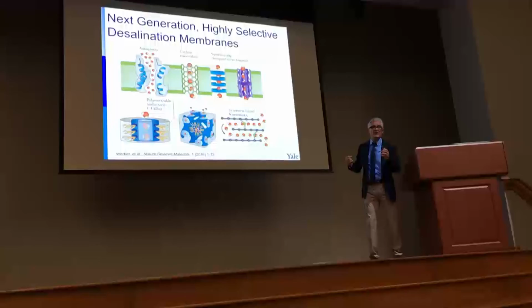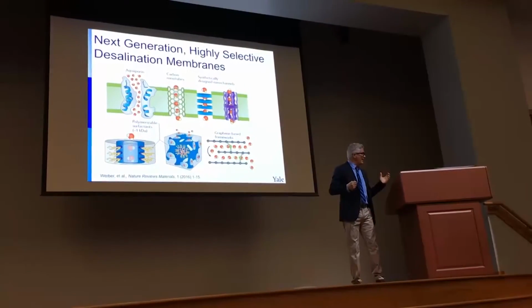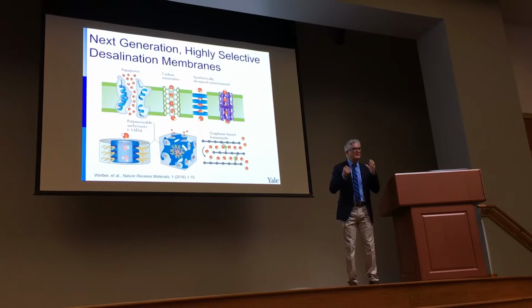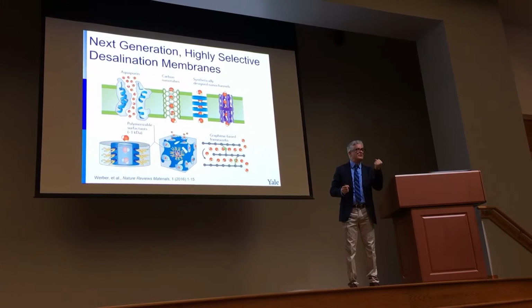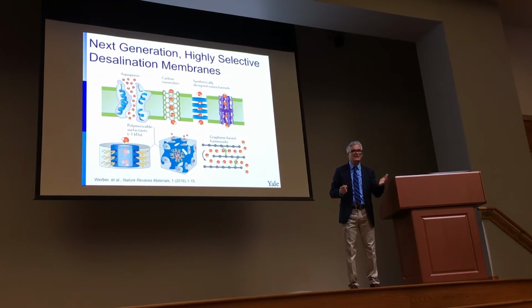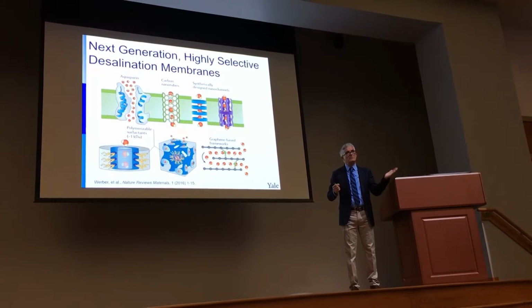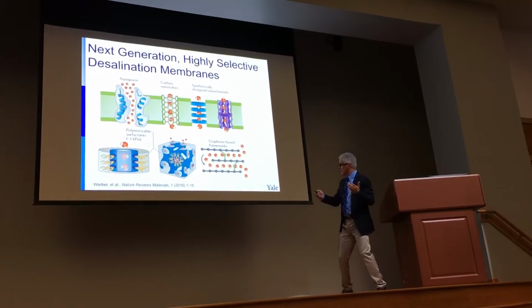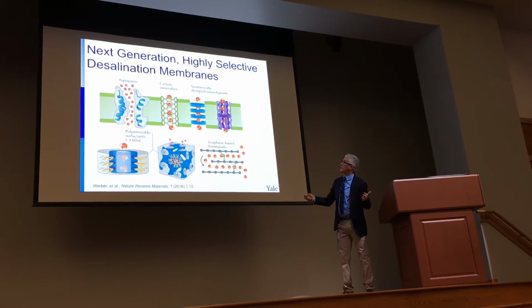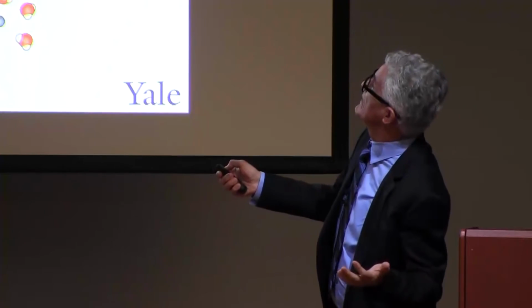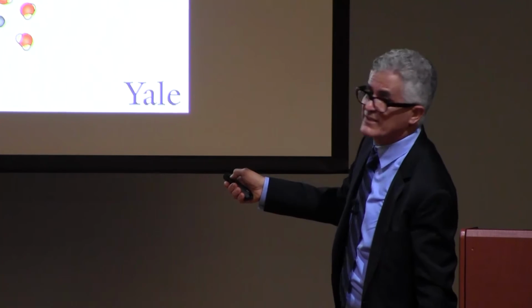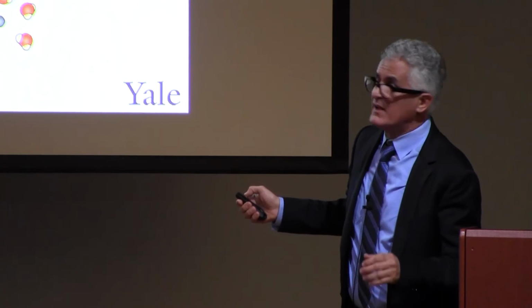So what we are trying to highlight, and again you saw it from the heading of the previous slide, what's really, really important is the selectivity of the membrane, not the water permeability, because the current water permeability of membranes is good enough. It will not improve the energy of desalination. And in this paper we discuss Aquaporin, I will tell you more about them, carbon nanotubes, and some other synthetic channels and graphene oxide that I mentioned here.